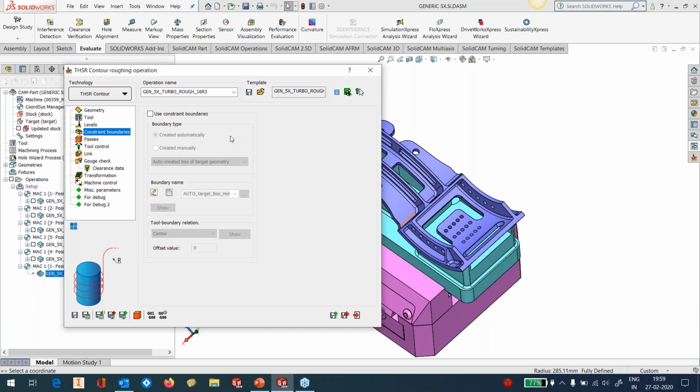By providing just the stock and saying I still have a center cutting tool, you actually tell the software that you can approach from outside, but in cases where you cannot approach from outside, you can ramp into the part. So it's not always essential to define boundaries with turbo HSR. You can skip the boundary definition if you have the stock definition properly.